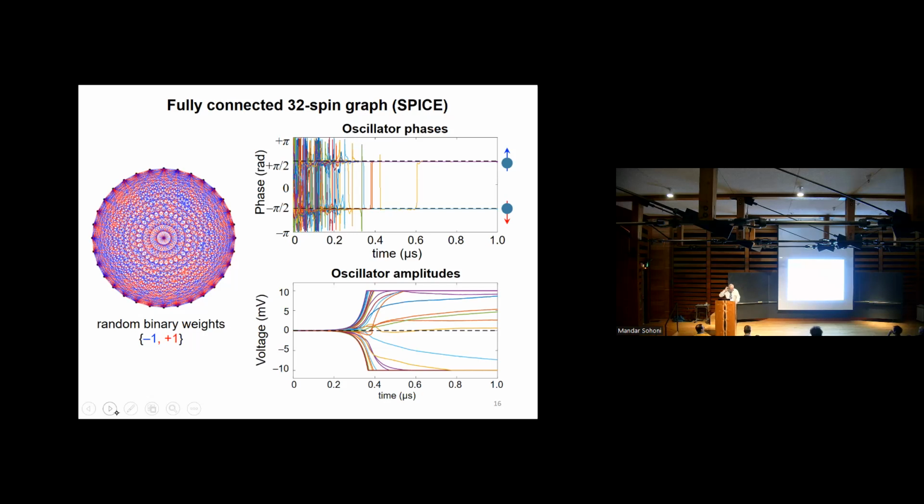We modeled each of these oscillators running at 1 gigahertz with a bandwidth of 100 megahertz and let them run. And what happens is that it locks in after a few hundred nanoseconds. The bandwidth of 100 megahertz would then correspond to maybe a clock cycle of 10 nanoseconds. And if you're within a few hundred nanoseconds, let's say 20 clock cycles, you have locked in to a definite answer. Now, I apologize for this complicated looking graph, but that's what happens.